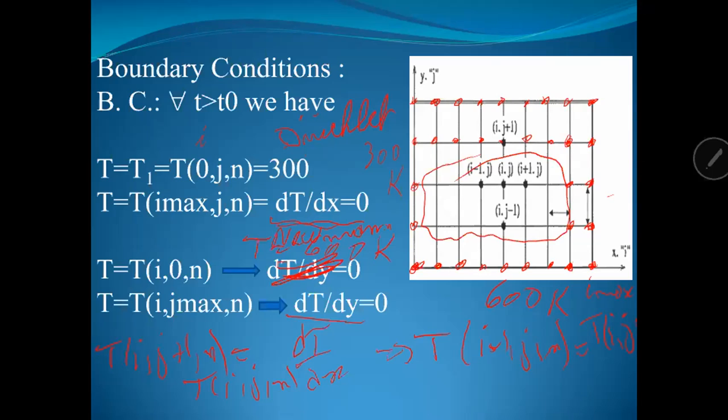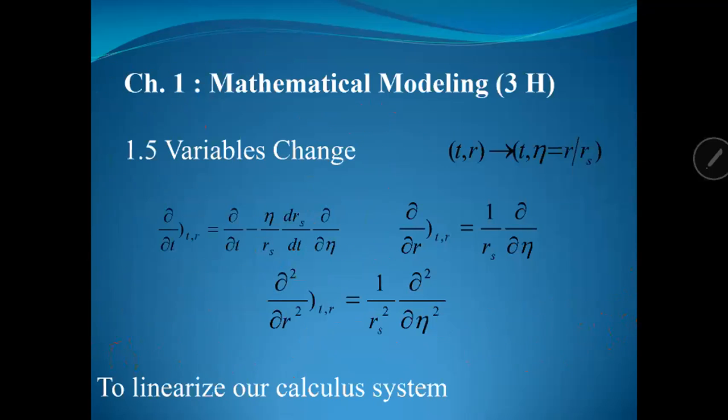Understood? Okay. Hidden initial boundary conditions. Now I can put also heat flux. I can put also Newton condition. Newton condition is when I put h delta T, convection. Okay, convection. I can put a conduction application in lambda, continuity of the conduction, lambda 1 dt over dy equal lambda 2 dt over dy.